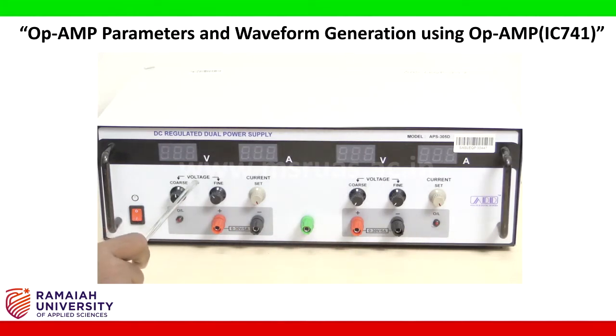So this is the voltage tuner and this is the current set tuner. In the voltage tuner we have two main categories: one is coarse tune and one is fine tune. If you want to tune your voltage to the maximum level, that will be done by the coarse tuner. If you want to tune the voltage at the minimum level, that will be chosen with the fine tuner.